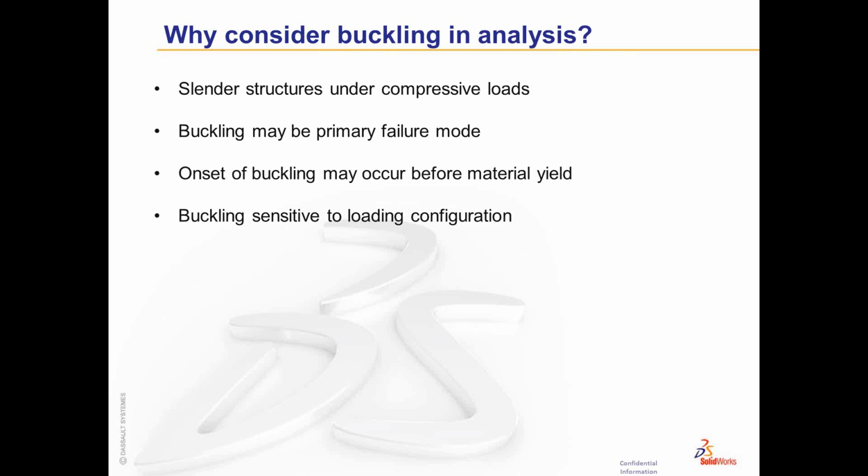Also, buckling calculations tend to be very generic, in that we have calculations in engineering texts that will give us equations to be able to calculate buckling load factors for traditional, simple shapes. Let's say a column that's loaded in compression.